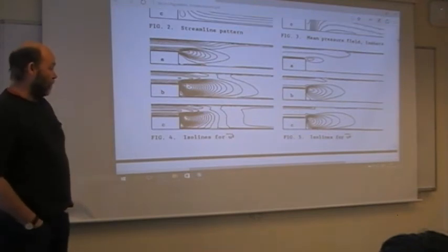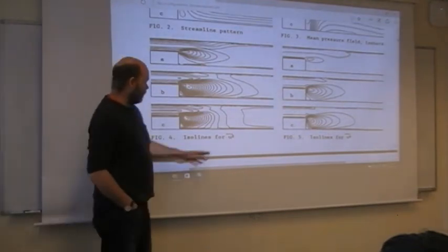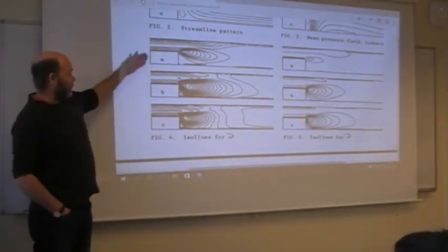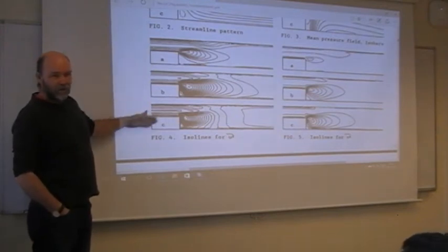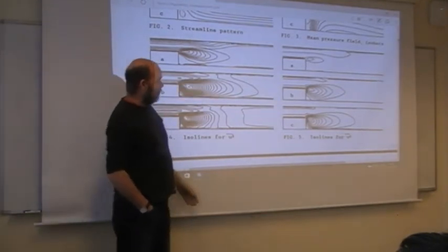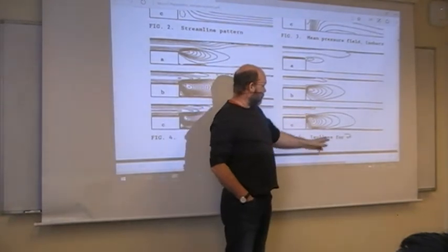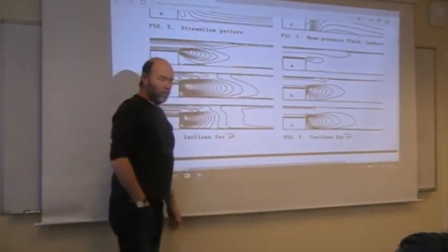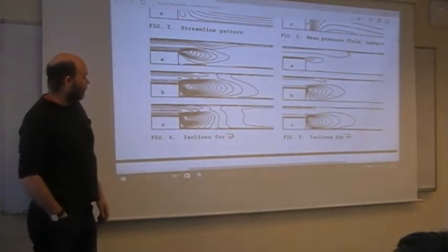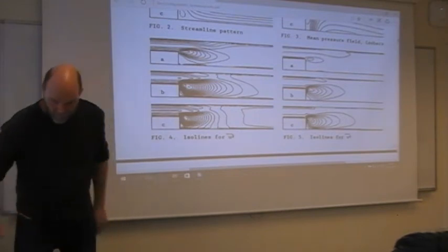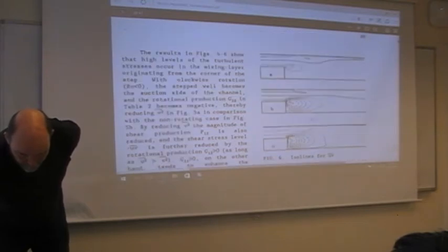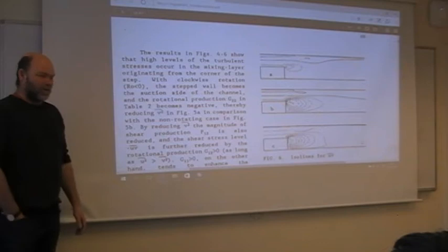Here are the different turbulent intensities, u-fluct squared and v-fluct squared, and clearly, yes, it's very inhomogeneous. In the streamwise direction they're pretty strong, in the cross-stream direction much weaker. So of course, it's a very inhomogeneous turbulent field. It's a very simple test case to set up, but not so easy to find.